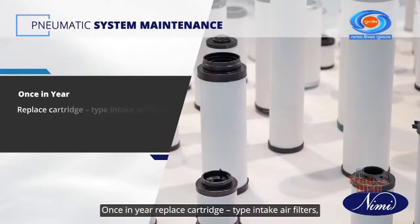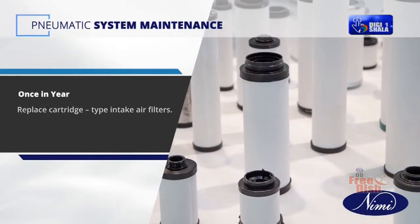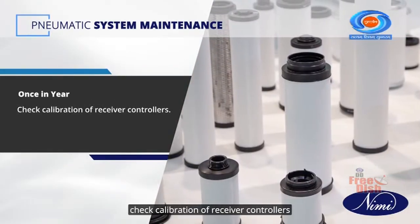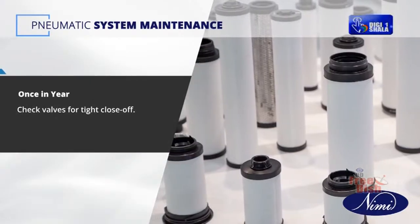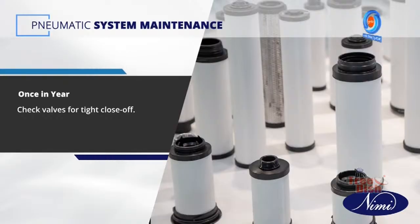Once in a year, replace cartridge type intake air filters. Check calibration of receiver controllers and the valves for tight close-off.